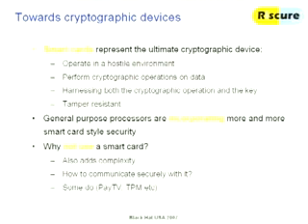Reasons for not using a smart card: it adds again to the complexity. If you've already got a very complex chip, why not make it a little bit more complex and just have it in one package? One issue is communicating with it. I'm not sure if you're familiar with the card sharing attack in the satellite business. If you've got a satellite set-top box and it's got a smart card, all the traffic from the satellite is going to the smart card, which descrambles the keys that are used for the video. But how do you get them from the card to the box? Well, over the smart card interface.